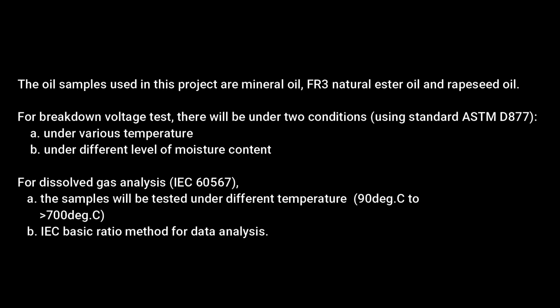And for dissolved gas analysis, by using standard IEC 60567, the samples will be tested under different temperatures, 90 degrees Celsius to 700 degrees Celsius or more than 700 degrees Celsius. The IEC basic ratio method is used for data analysis.